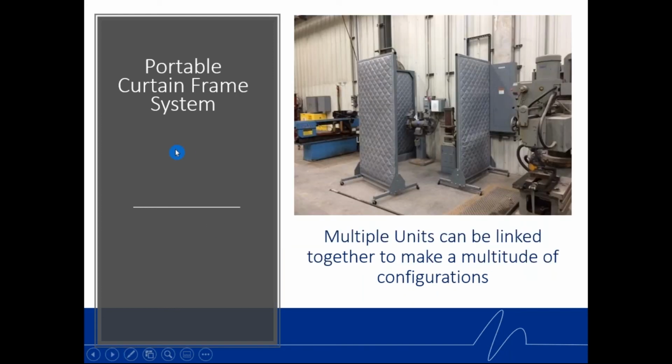Now, another one is multiple. You can have multiple of these portable roller curtains. Now you can get a half dozen or a dozen of these, and as they get closer to each other, you can use a mass loaded vinyl to cover this corner and connect each. So you can make this in many different shapes where they come completely together and then close off with Velcro on this arm and this vertical arm, and then a mass loaded vinyl. So it's a really neat system. That was a picture I had of some that were just in storage. They weren't actually using them for that grinding process there.